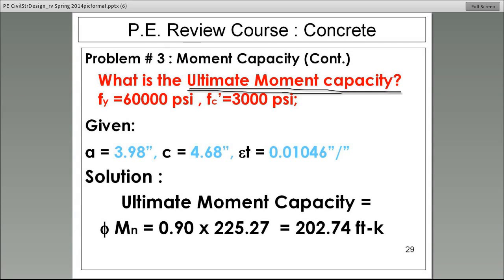So instead of allowing the building or the member to be exposed to the theoretical ultimate moment, or the nominal moment as we called it, they calculate what they call the ultimate moment capacity and use that in their equations. All right, now, obviously, tell me, would you want this ultimate moment to be less or higher than the theoretical moment? Yeah, absolutely. You want it to be lower. So take a look at the very bottom of this page.